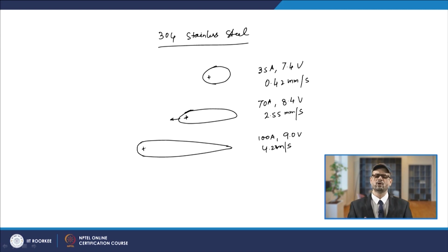Now, if you do it for stainless steel and if you do it for aluminum, you can more visibly see it in the case of stainless steel, because aluminum is more conductive. There has been a certain observation, with a particular heat input and also the velocity, especially at larger velocity, a sharp pool end was seen in the case of stainless steel.